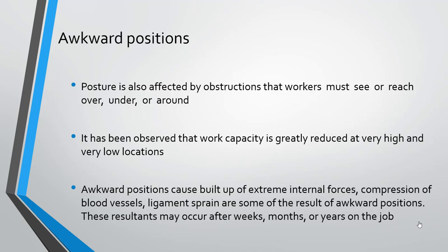Posture is also affected by obstructions that workers must see or reach over, under, or around. If the work is located overhead, as often occurs in manufacturing settings, workers will have to stand with their hands above their heads, and if the work is located on the floor, the workers may have to bend or stoop. It has been observed that work capacity is greatly reduced at very high and low locations.